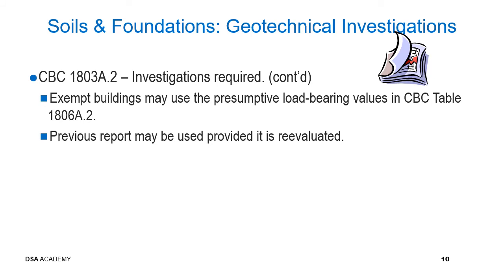Exempt buildings may use presumptive load bearing values in CBC Table 1806A.2, or they may use previous report provided it's reevaluated by the geotechnical engineer for its validity.